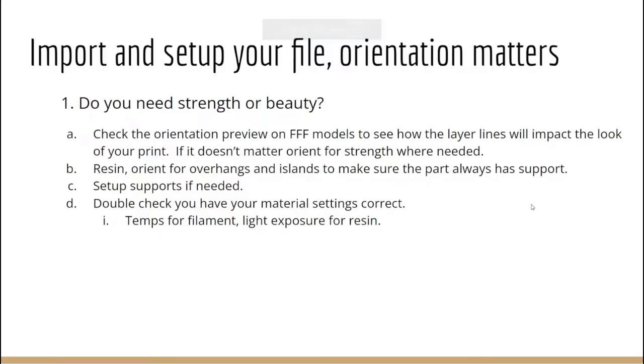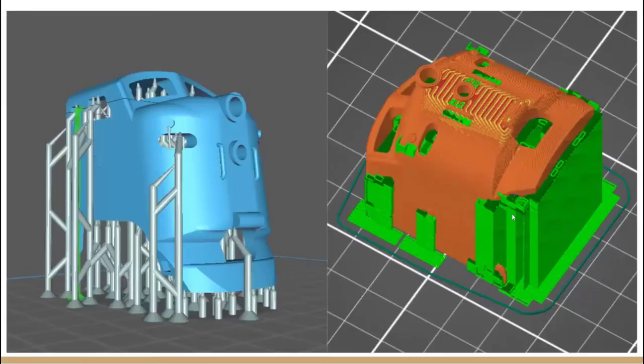All right. Yeah, so strength on these models is another thing. Resin and the FFF, which is what we were just looking at with the layers, are a little bit different. So orienting the parts in certain ways will allow you to get the maximum quality and strength properties. In resin you can print in almost any orientation, because resin is isotropic, which means any direction that the thing is manufactured, the strength is equal. On any piece that you're looking at, the strength of it will be the same, uniform.